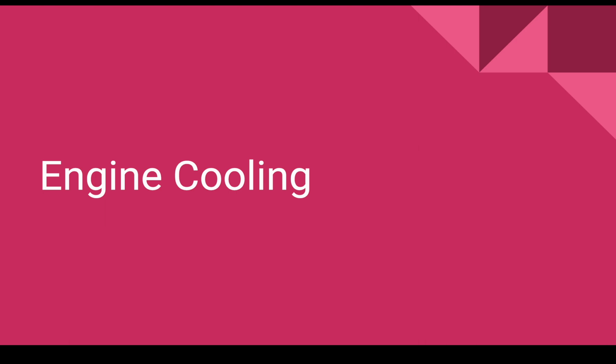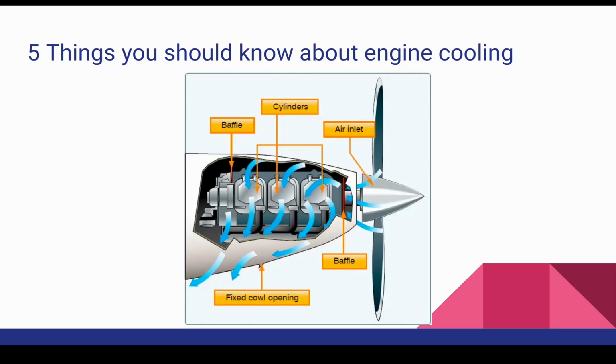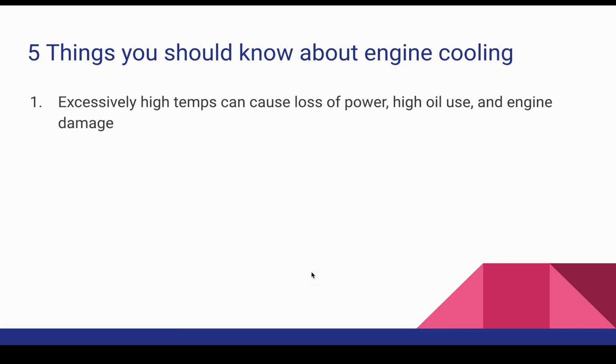Let's talk a little bit about engine cooling, how engines get cooled. We talked about oil systems that help with cooling, but a lot of engines in general aviation are actually just air cooled. There are these big ports in the front that pull air in, and they use something called baffling to help move the air around the cylinders, and then there's some sort of exhaust for that hot air to exit the plane. As you're flying forward through the air, it's just forcing cooler air into there.